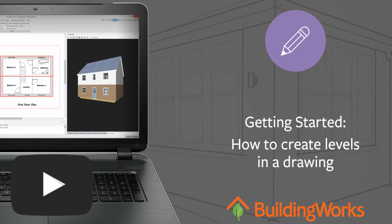In this video, we demonstrate how to set up levels for a multi-storey building. Once you've created your ground floor level, you can copy it to create additional stories if the external walls are being built to the same specification. Levels are important because they tell BuildingWorks where each story begins and ends. They stack the different stories of your design to create the 3D model and elevations. To create an attic level, take a look at the videos on drawing attics for further help and advice.